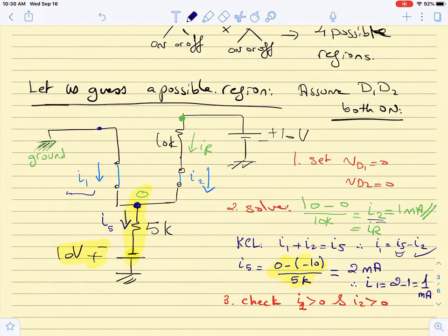Is this clear? So how can it be possible that there is a current between the two nodes when there is a voltage difference? Because we assumed an ideal scenario, and we said let us assume that the diode is a short circuit. But then the short circuit compensated for the difference in the current between the two branches.